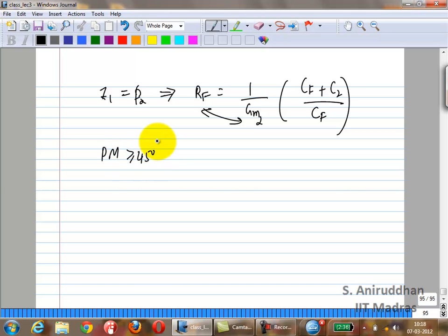So before that, what we'll do is we'll see what happens if you need the phase margin of 45 degrees. In this case, P3 has to be at omega u, right? So this is the condition you get. Let's say in this case greater than or equal to. Because now you have cancelled out P2. P3 is the next pole. And to have 45 degree phase margin, you can increase your omega u now, such that P3 is right at omega u.